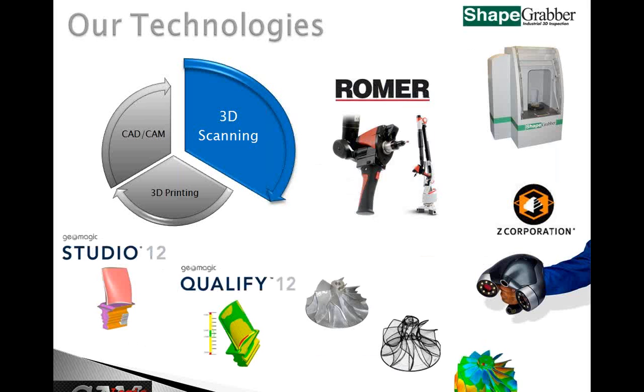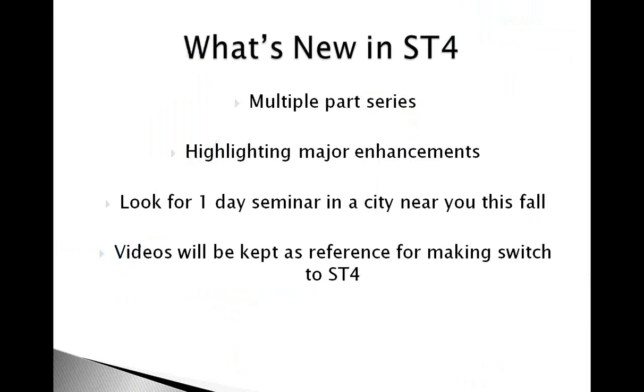And then 3D scanning, 2 purposes really. One is reverse engineering. You can take an existing piece and go out there and measure it, get your specs, churn that back into a CAD part. Also, you can take pieces straight off the line, put them in the ShapeGrabber, and scan them around. So you imagine taking that piece right off the line, scanning it, knowing that the pieces that are coming off of the assembly line there are good.